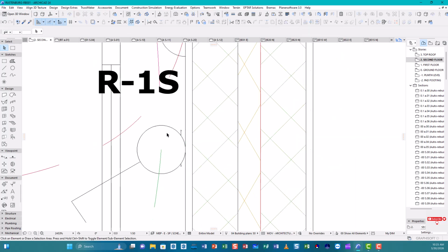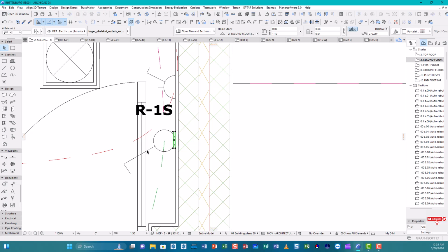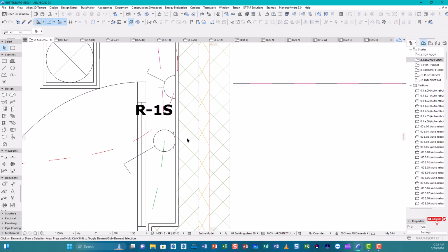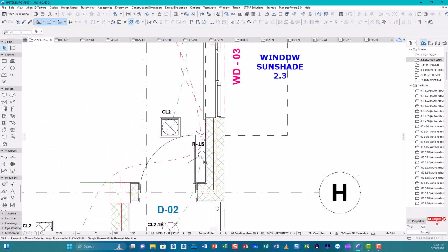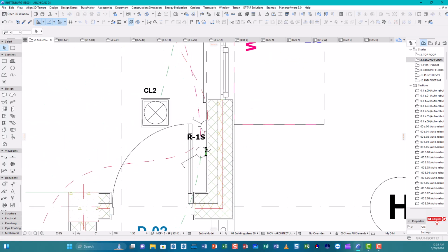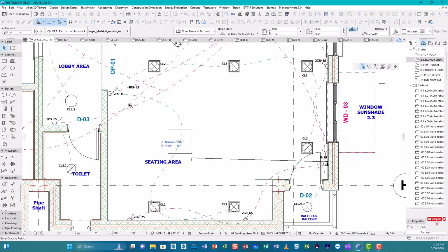Even if I increase the scale here, it's the 3D object of this one pole switch, so we're not going to impact the view on the plan. So this is a single pole there. I'm just going to click on it and copy it to every single pole on this second floor, instead of just mirroring it.